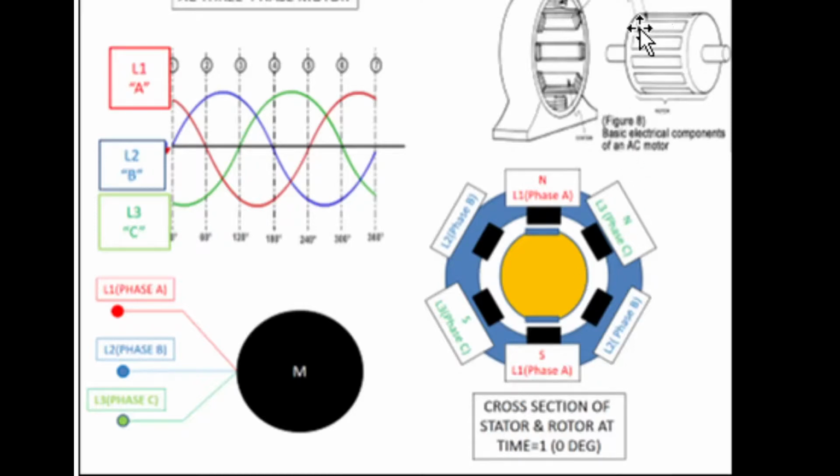Now, the rotor, that's the center part of the motor itself, sometimes called a squirrel cage, because it has these horizontal bars inside. Kind of looks like a hamster cage, if you want to call it. In any regard, it's made of these iron plates inside. Now, if you remember from our magnetism section, obviously iron and a magnet are attracted to each other. So when I magnetize these top two magnets, that magnetic field goes through the iron, and that's what develops the attraction here.